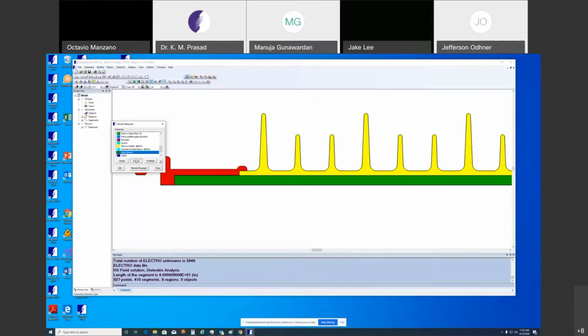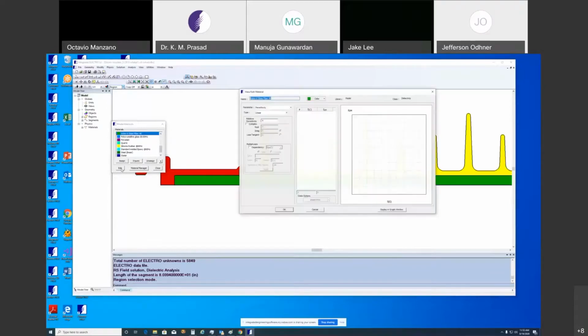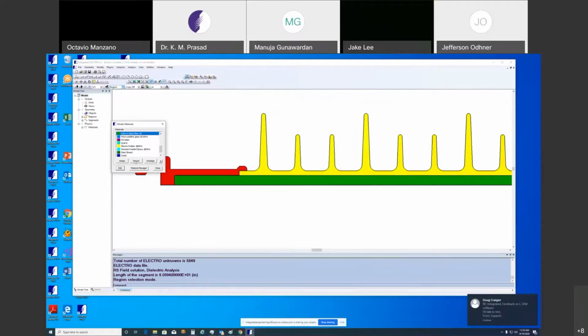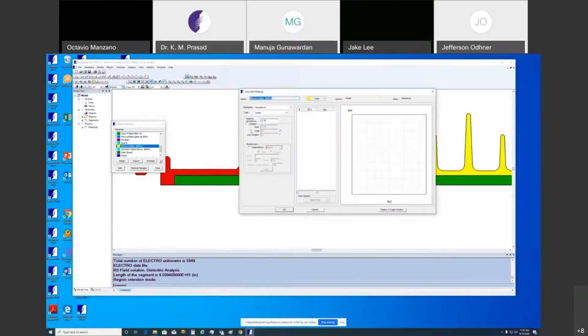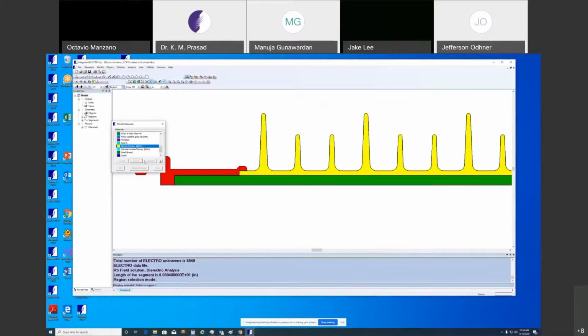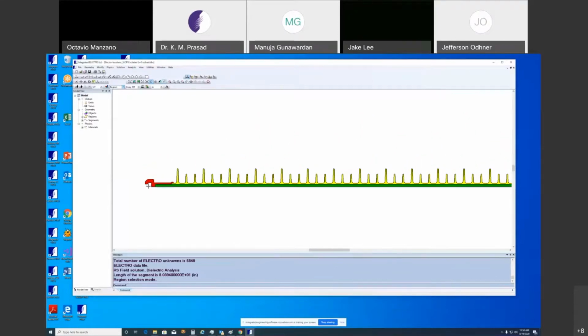material. This material is silicon rubber. All the sheds are silicon rubber. And this is nylon 6 fiberglass. It has got a permittivity of 4. And this silicon rubber, it has got 3.45. And this they put as copper. This is only for beauty purposes because they put a boundary condition there.